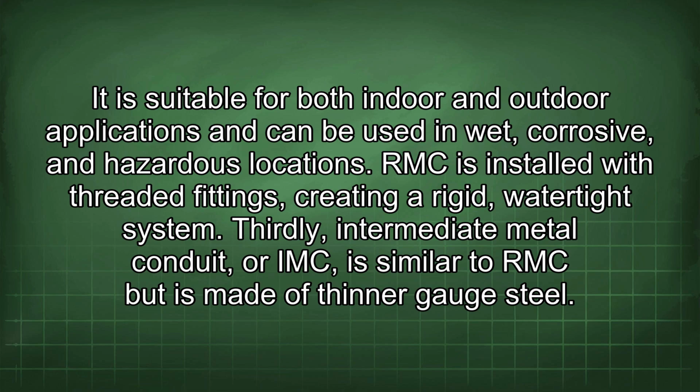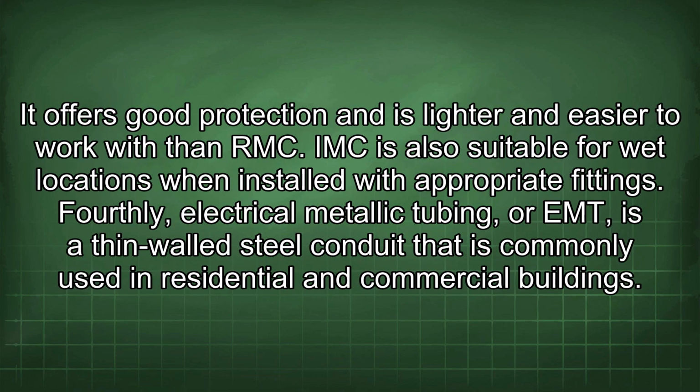Thirdly, intermediate metal conduit, or IMC, is similar to RMC but is made of thinner gauge steel. It offers good protection and is lighter and easier to work with than RMC. IMC is also suitable for wet locations when installed with appropriate fittings.